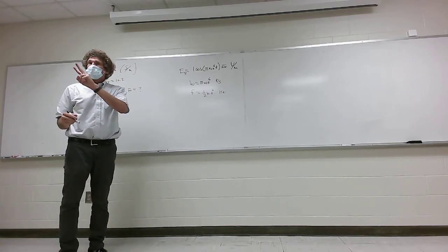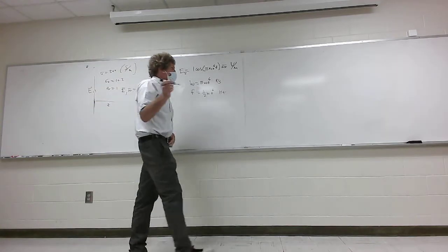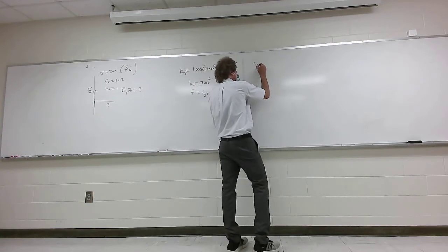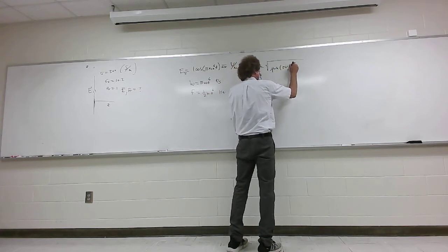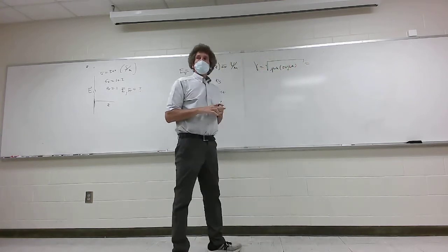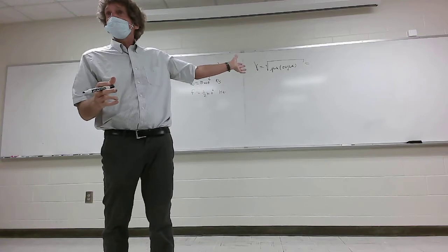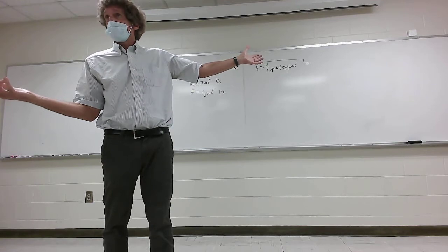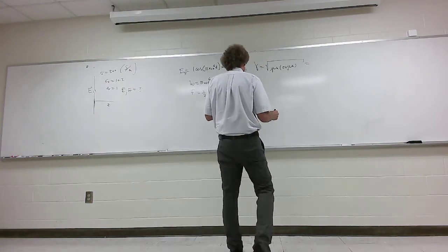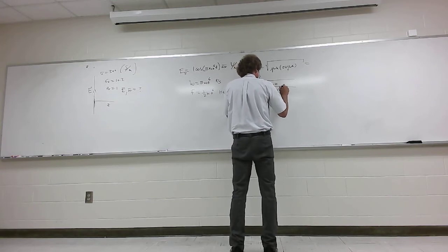Now that we have that, I want the propagation constant and the intrinsic impedance. Once you get those, everything else falls into place, but you have to have both. First, the propagation constant gamma is the square root of j omega mu times (sigma plus j omega epsilon). If you are ever uncertain whether it's a good conductor or a lossy dielectric, just run the equation. You have expensive calculators. You'll get a real and imaginary part. The second is the intrinsic impedance, the square root of j omega mu over (sigma plus j omega epsilon).